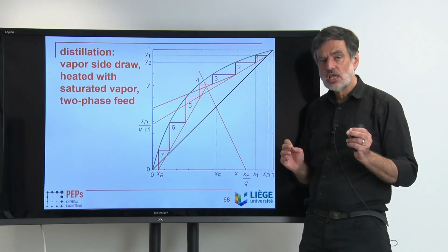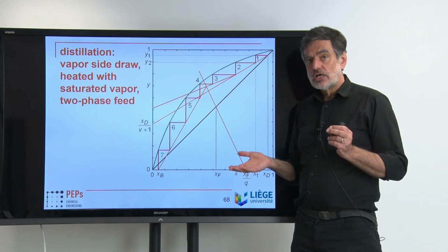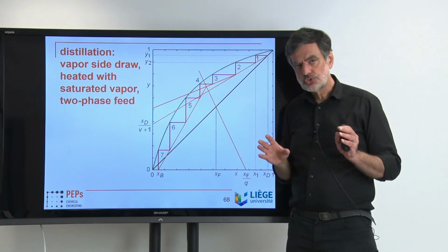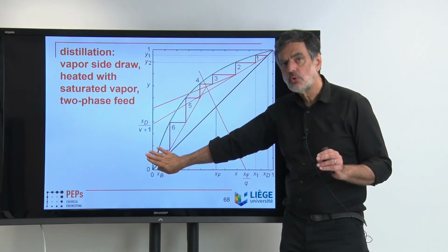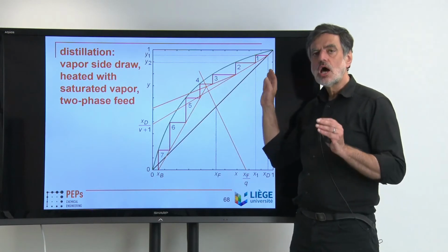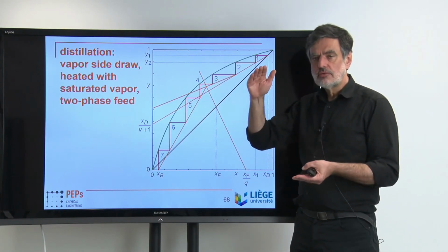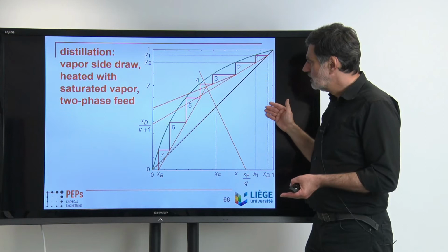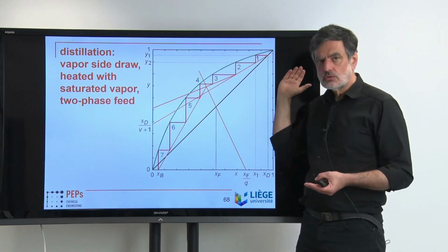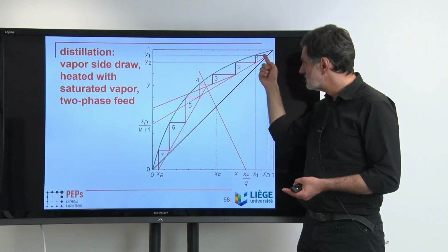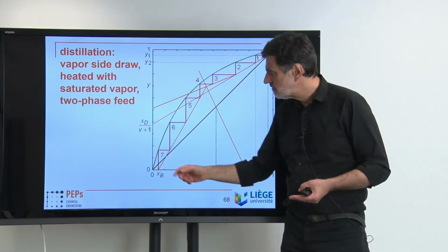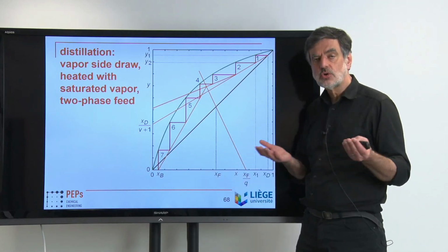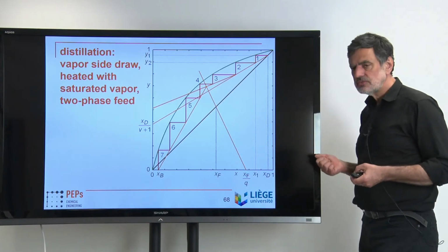And the second question now is, do I have a total or partial condenser, which means this is possibly my partial condenser, or do I have a partial or total reboiler? So this is possibly my total reboiler. And only the remaining theoretical stages are then to be realized in the separation-active part of the distillation column. As I said, typically the condenser is a total condenser, so that is still to be realized. This is not the partial condenser, but here you frequently have a partial reboiler at least, so that corresponds to your reboiler as a frequent case. But as I said, you always have to check individually for the specific case that you have.